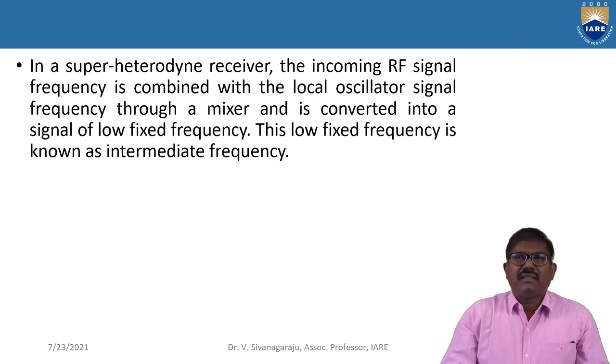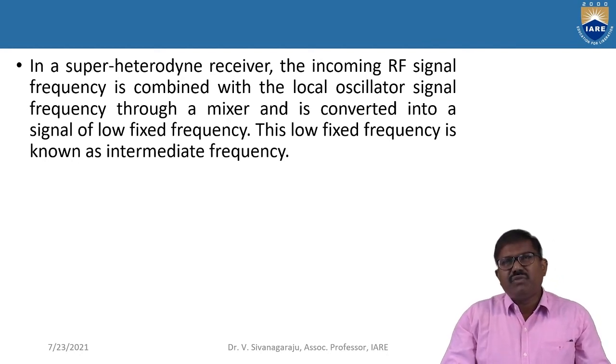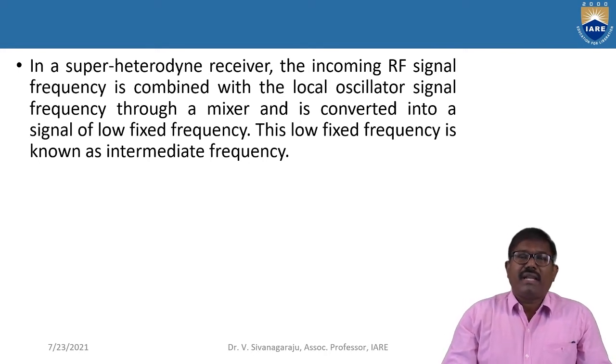So this is the very simple operation of TRF. That's why it is missing this IF amplifier stage. So that's why the selectivity of this TRF is very less. So we go for super heterodyne